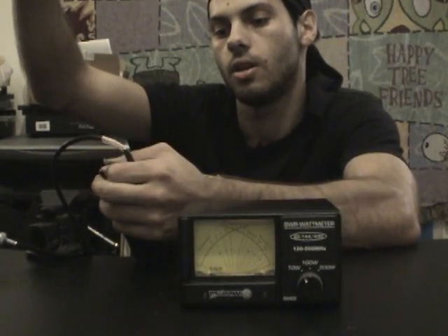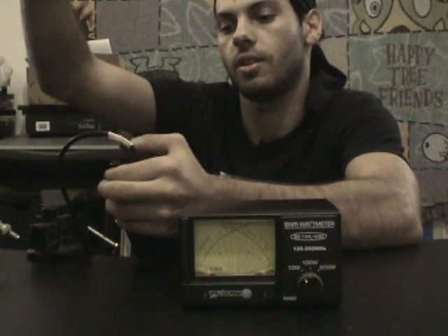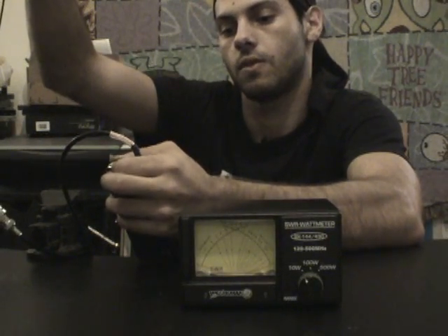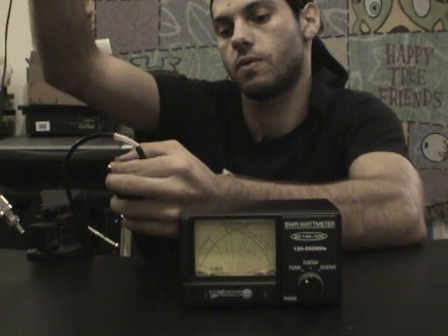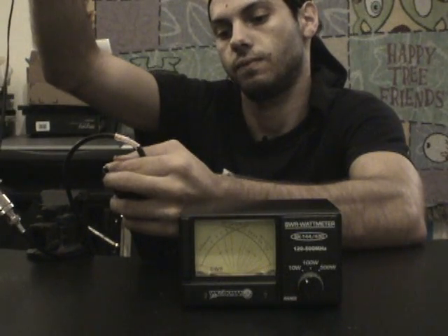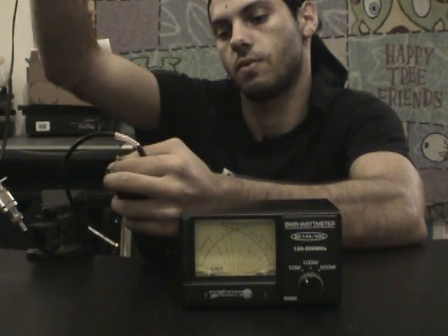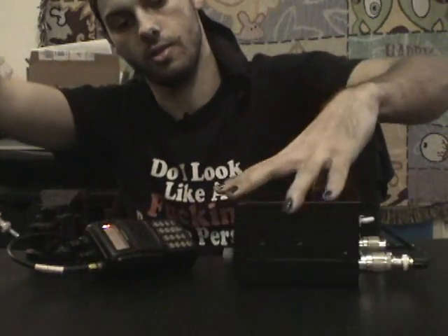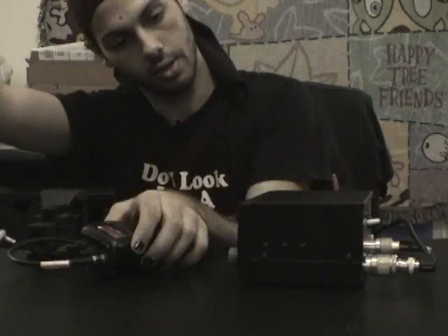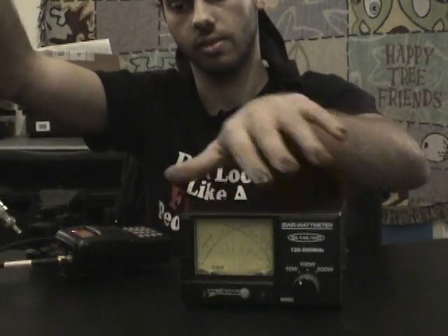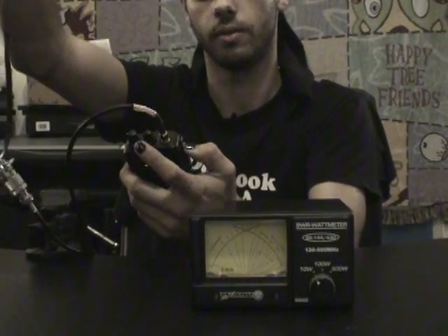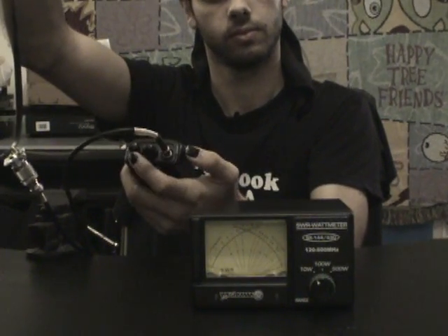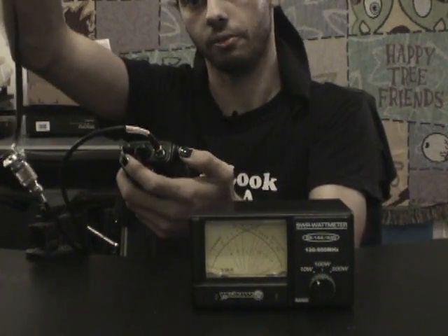Now let's go down to a quick 70 centimeter ham radio band. Give me 1 second to tune this in. I'm going the wrong way. Where are you? There we go. Alright. Now let's actually turn down my transmit power, just in case the SWR is that high, we won't blow out the radio. Wow, it's actually doing 2 to 1. At least we're hitting the repeater.